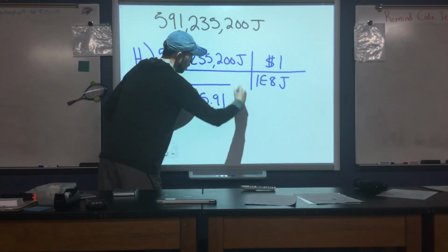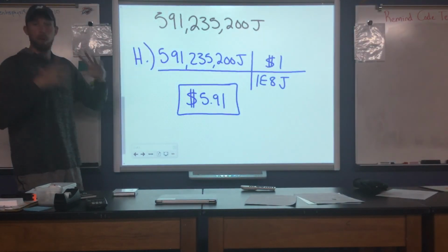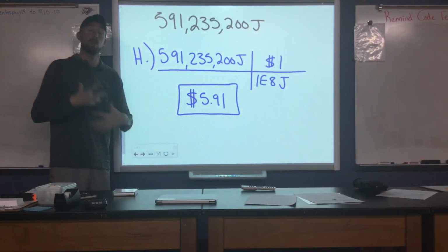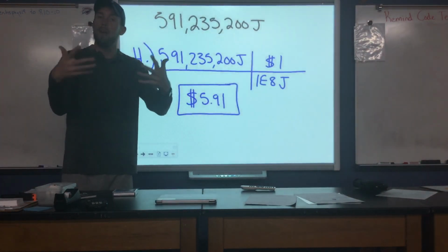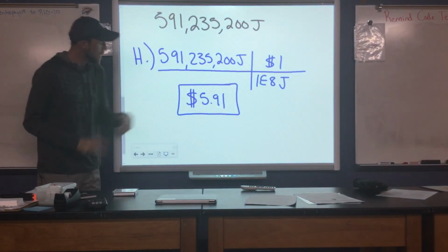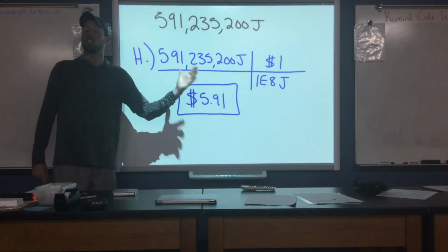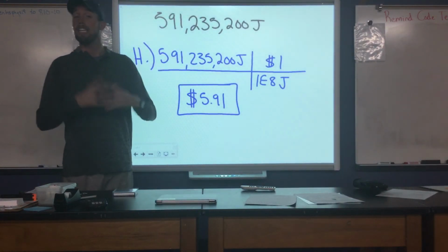So as you notice, as we were doing this, the process looked very, very similar the second time around. We just found a new heat transfer rate for our new window, and then scaled that up to a month, and then used our rate to figure out how much money we would be spending. Now you'll notice here that number is much, much lower. Something that might be a little bit more realistic if we were dealing with something like an energy efficient type of window.